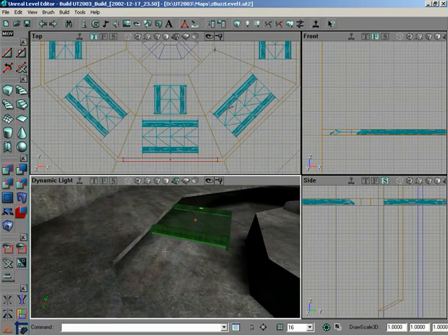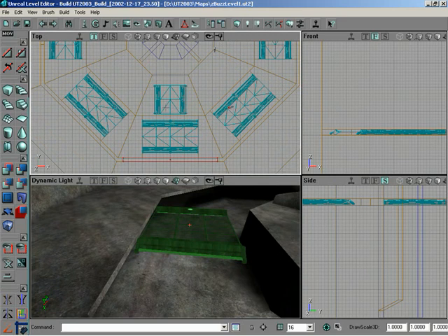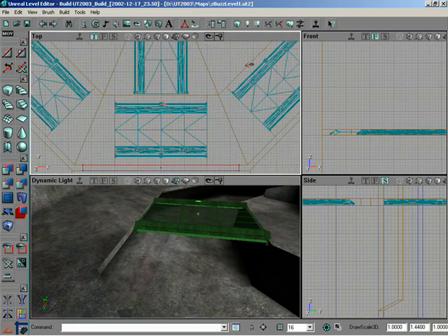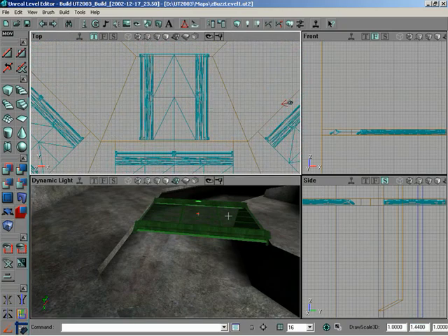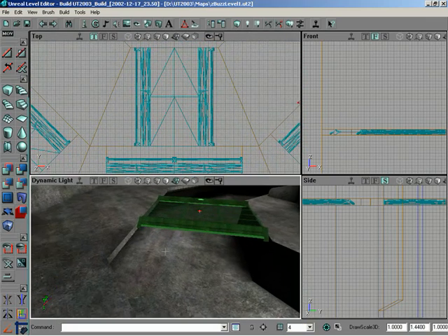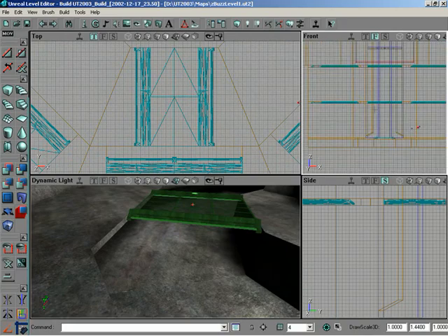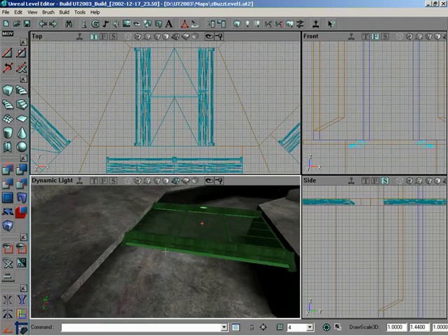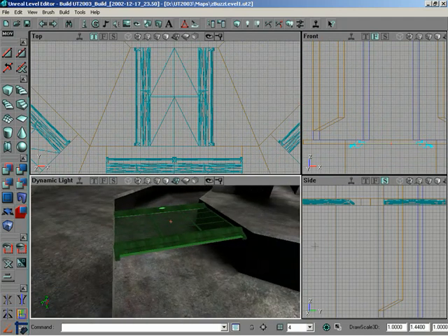But you see that it doesn't quite fit. And if you added 2, there would be too many. So what I'm going to have to do is scale it out just a little bit. Under Draw Scale 3D, I'll grab the second axis and set it from 1 to 1.44. Hey, very nice. I might have to drop my grid a little to get that to snap just right. Let me try 4. Zoom in here, and that's very close. That should be right about there. Let me zoom in from a front view just to check the height. Move it down just a little bit. And there, now I've actually got the walkway across, and it fits.